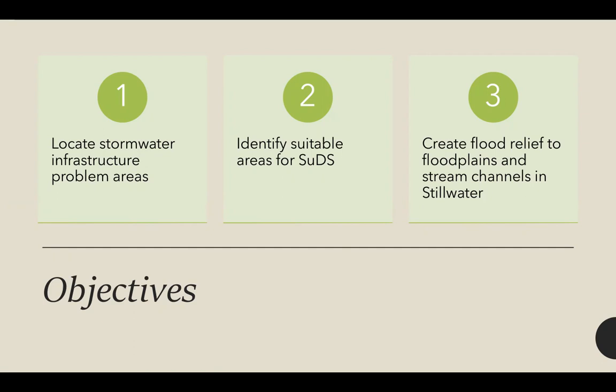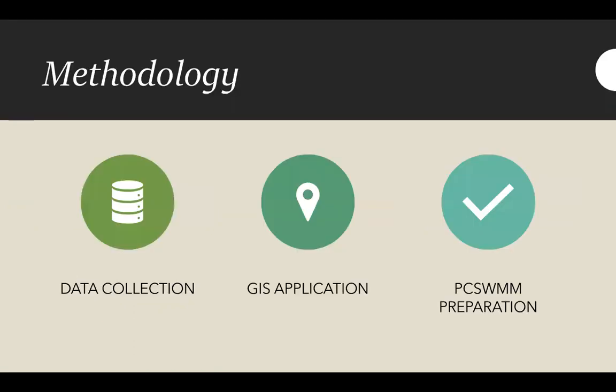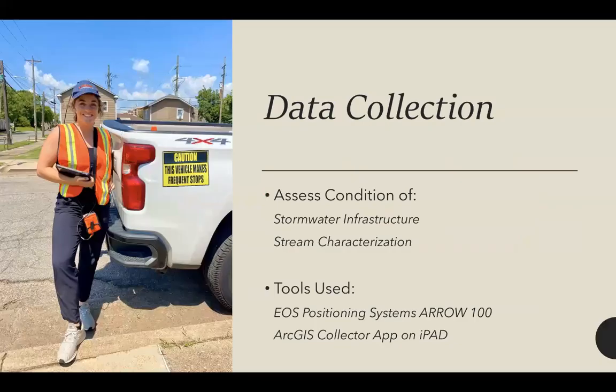And for the modeling section, using PC SWMM of pre and post SUDS integration with GIS defined stormwater sewer infrastructure zones will also help stormwater managers see the economic, social, and environmental benefits of implementing such practices. So for my methodology, there was data collection, GIS application, and then the PC SWMM preparation.